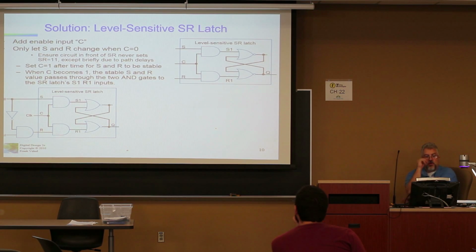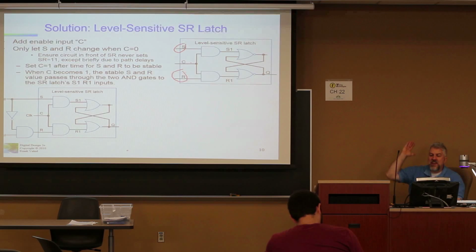And so what we do is we introduce with sequential circuits a device, or an input, called a clock. And so that means that we're going to rely on a clock signal to actually work with our input and say, we're going to let this input and this input settle, and then we will give you this clock signal which says, now latch this into our SR latch.